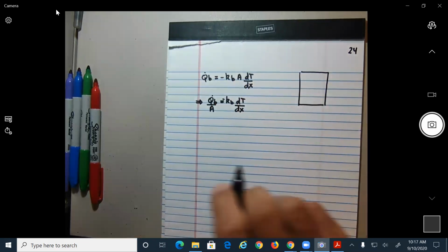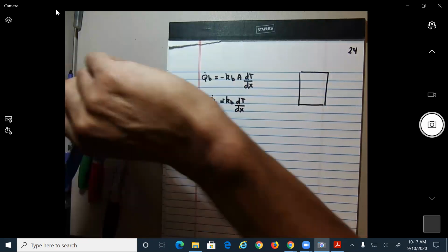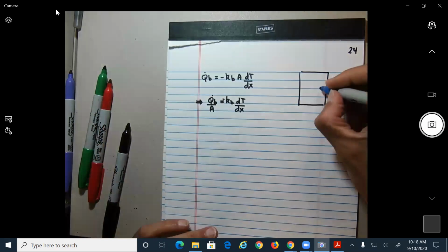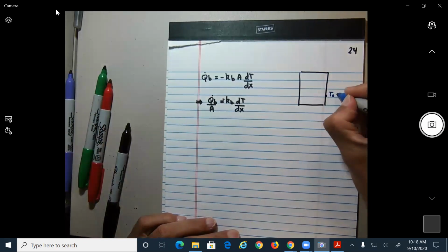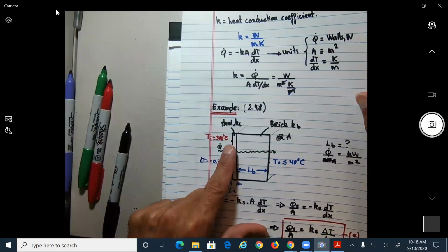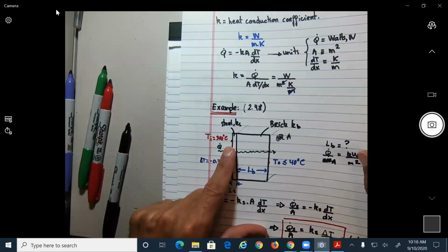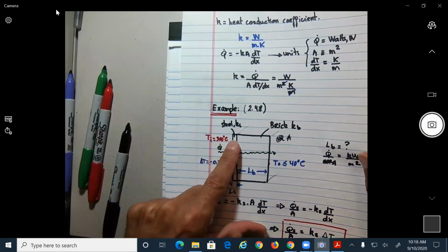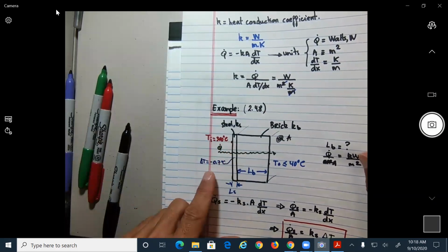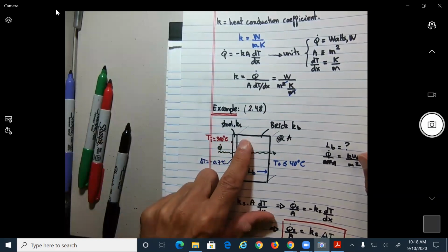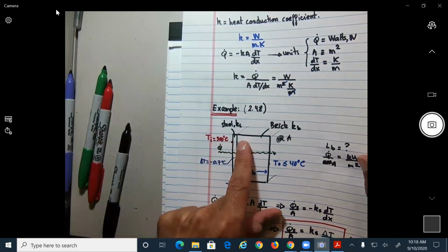Okay? So over here, we know the outside from this figure needs to be, let's say, lower than 40 degrees Celsius. Now here, the inside, this problem is not well spelled, but they say, okay, if this is 300 on the outside, and we know that the heat is going to decrease 0.7 degrees on this one, what should be the temperature right at this edge over here between the steel and the brick?